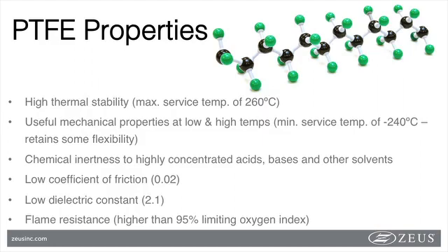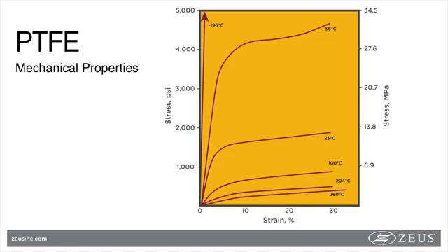There are no known solvents for PTFE below its melting point. It is, however, attacked by molten alkali metals, chlorine trifluoride, and gaseous fluorine. Although PTFE doesn't flow, its melting point as measured is very high, upwards of 320 degrees Celsius, which allows this material to have outstanding performance at extremely high temperatures, up to 260 C.